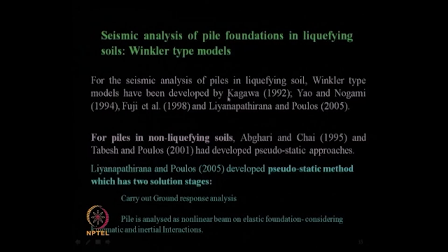So, for the seismic analysis of pile foundations in liquefiable soil, the initial researchers mentioned the Winkler type model. As we know from the basic concept of any soil structure interaction course, soil structure interaction courses always start with the basic concept of the Winkler beam model, right. So, Winkler springs are considered below a foundation analysis when we consider how the foundation interacts with the basic foundation soil. So, foundation with respect to soil we calculate through the Winkler springs.